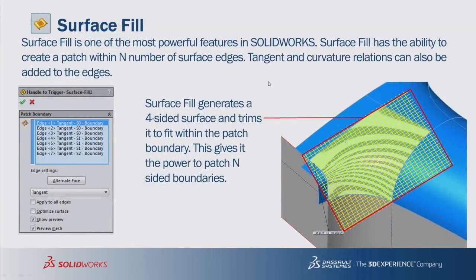Finally, the surface fill. The surface fill is probably the most powerful feature in SOLIDWORKS, in my opinion, because it gets you out of trouble and little modeling situations when you're painting yourself into a corner. Surface fill is going to get you out of it. So what surface fill is great at is generating surfaces between n number of surface edges.